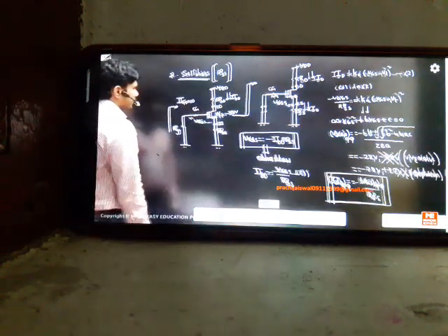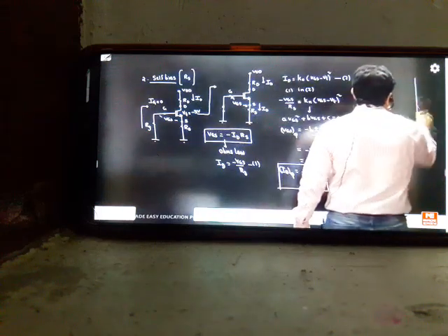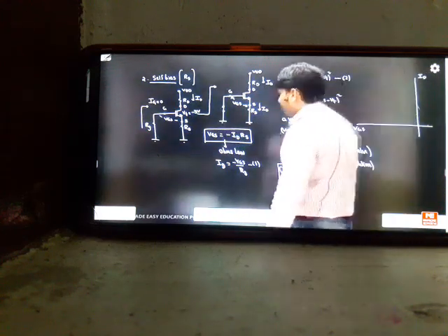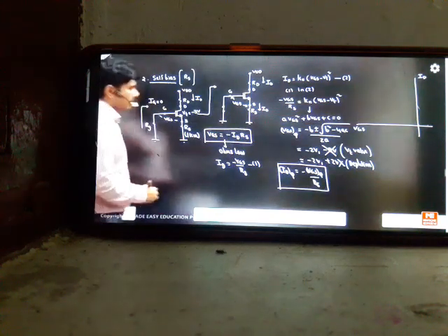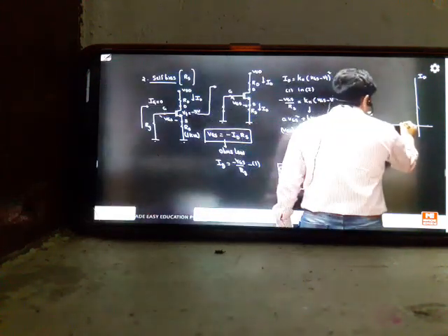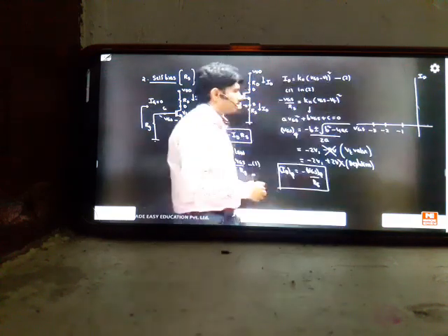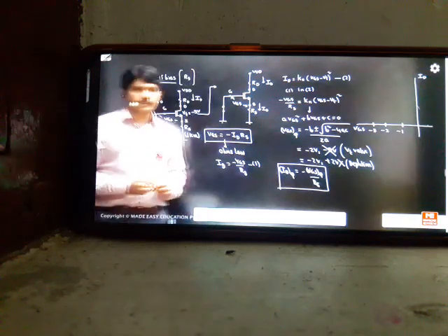The load line graph for this question, that also we will complete. See here, I'm drawing the load line graph. This is your graph, VGS, and this is your ID. For example, we'll fix this source biasing resistor as 1K. In the lab, I fixed RS as 1K. Then to get the load line, suppose VGS is minus 1, minus 2, minus 3. I've taken some samples in the graph. Gate to source voltage is minus 1, minus 2, minus 3, and the RS value is fixed at 1K.